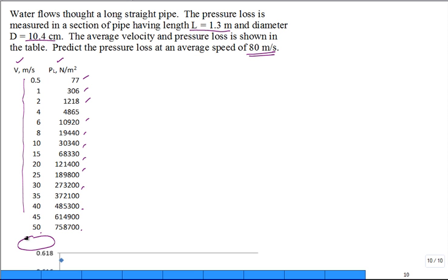This is a case where you'd like to justify extrapolating the data, and if it's in a Reynolds number independent regime. So what we remember is that we have a pressure loss, and we cast that in dimensionless terms. What was that? We divided by the 1/2 rho v squared. Sometimes they give it a name, sometimes not. But here in this chapter, did they call that the Euler number? So the Euler number is a function of the Reynolds number. Okay?